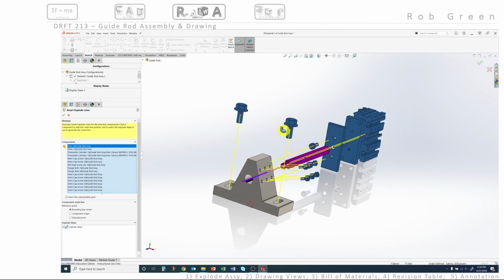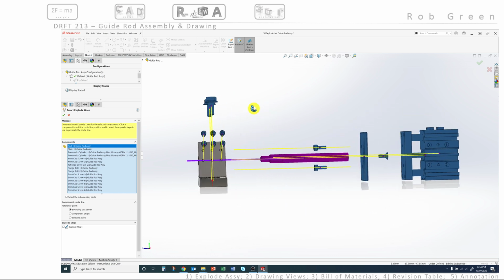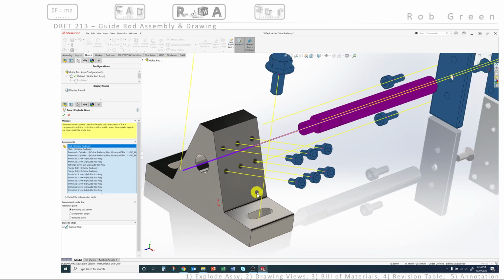So now I'm perfectly free to rotate this view and look around and see what I want and what I don't want. And if you look on the face of my drawing, I have an assembly line for only one of these 3mm screws. So for pure accuracy, having a line for all 6 is the most accurate, but yet there are so many lines and some crossing lines that quite frankly it's not very clear. So I'm simply going to select a bunch of them, like 5, and delete them. I'd like to keep this lower left because it's the closest to me in the drawing view.